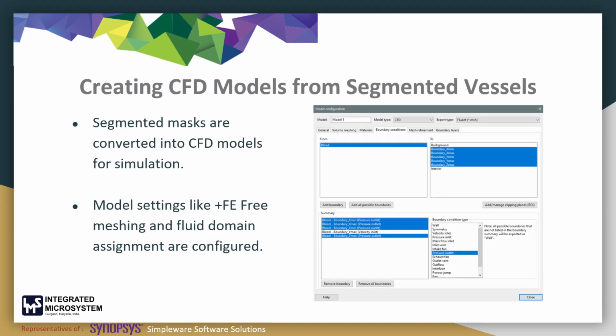Now creating a computational fluid dynamics model from segmented vessels. So segmented masks are converted into computational fluid dynamics models for simulation, and model settings like finite element analysis, free meshing, and fluid domain assignments are configured.